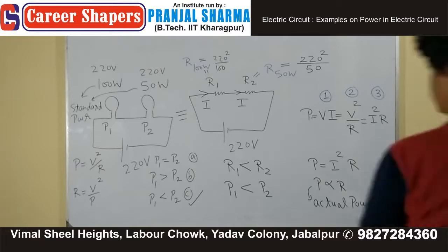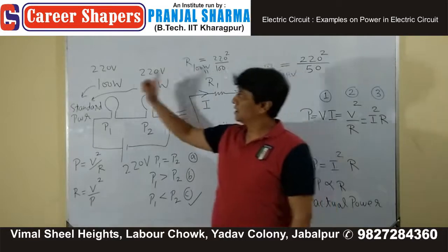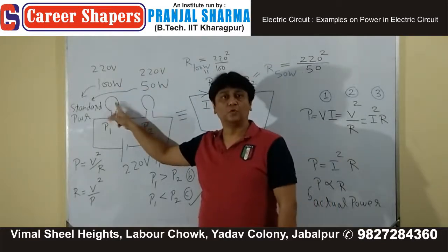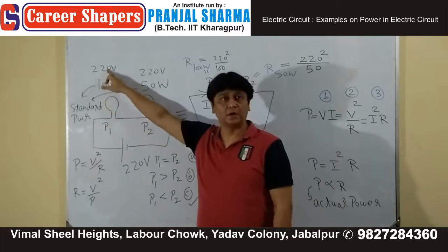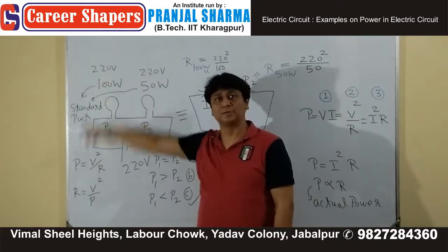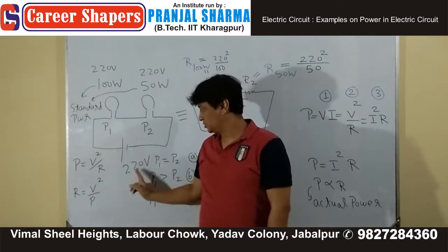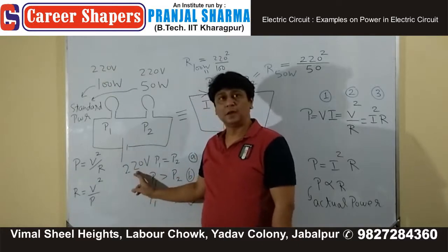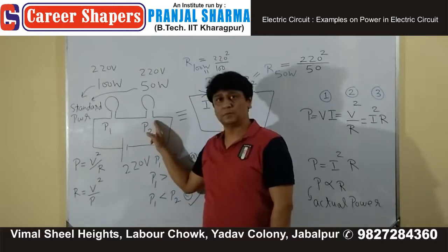Well, nobody answered it correctly. This bulb will give you 100 watts when you connect it to a 220 volt supply, but you have not. This 220 will be shared by this bulb and this bulb.